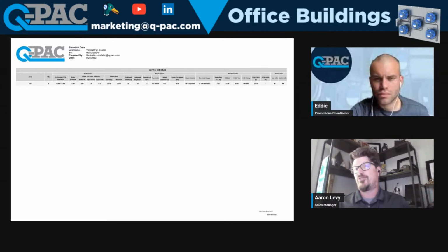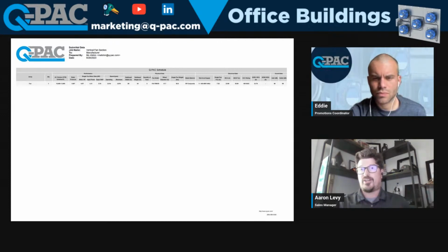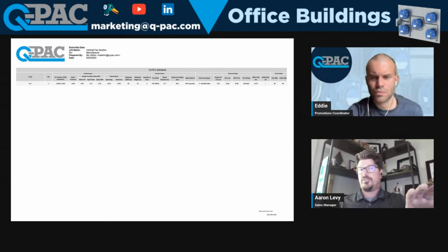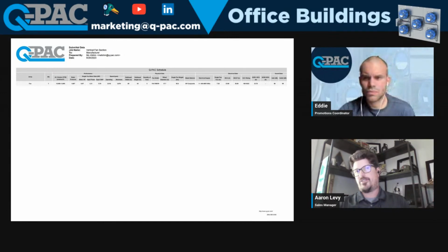So for an inspector, your life's a lot easier. All you're really doing is checking, because we do all the inspections and testing before the systems go out to make sure all the communication lines are great and everything works. So really all you're inspecting is their line voltage coming in from the building to our terminal block inside the fuse block inside the disconnect, and then their connections between the terminal block in the disconnect to the terminal block inside the quick connect box. Short of that, the rest of that's all in Q-PAC. So it should make your lives on that standpoint relatively easy.